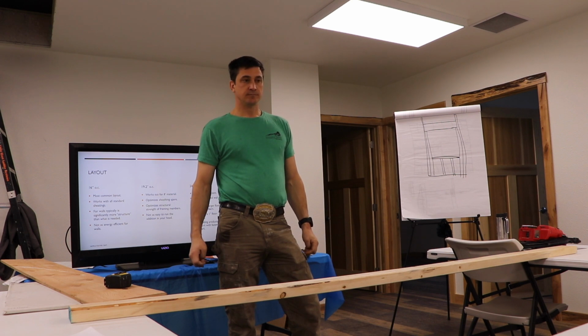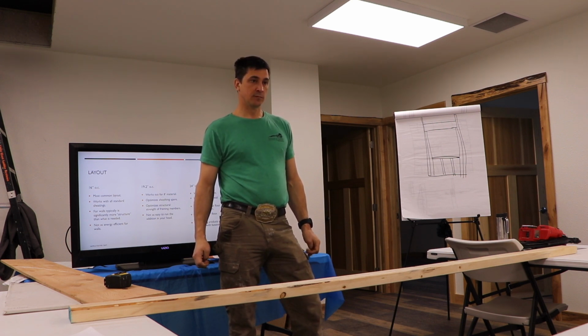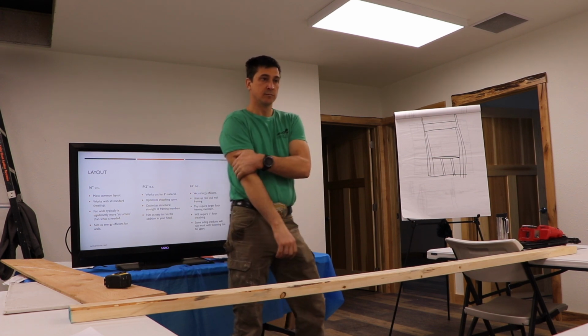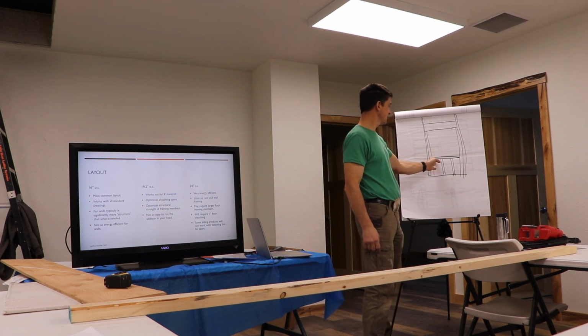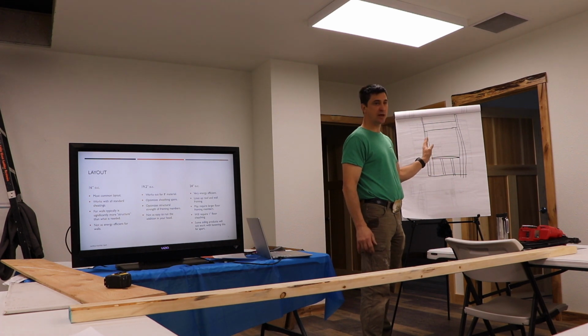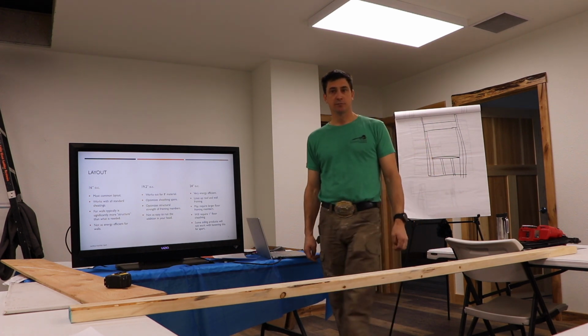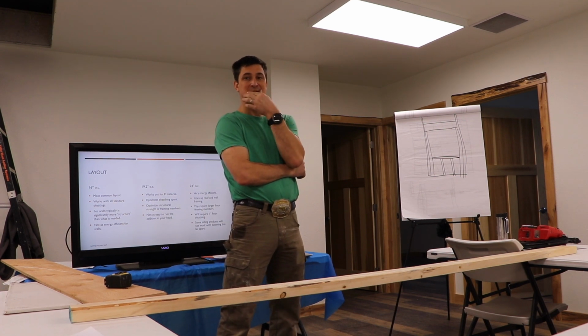What if underneath your window you only have 2 studs or jack studs, and one's really close to the king stud? Just push it all the way up and leave it there. You could do that. Yeah. Sit it there instead of putting it 3/4 of an inch away. Yeah, that would be an excellent call. We do that a lot.